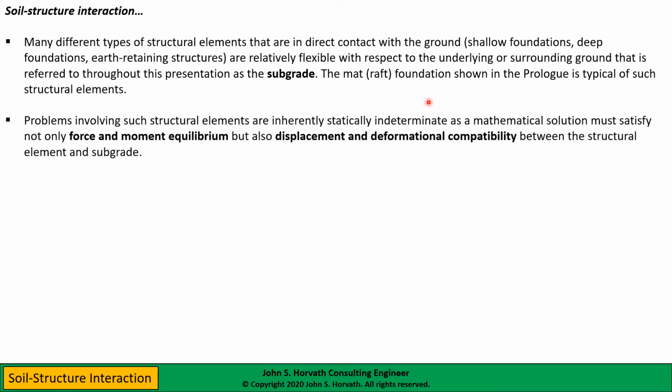Problems that involve such relatively flexible structural elements are statically indeterminate, because in order to come up with an acceptable mathematical solution, you have to satisfy not only force and moment equilibrium, but also displacement and deformational compatibility between the structural element and the subgrade.